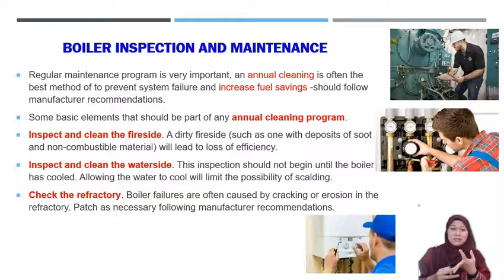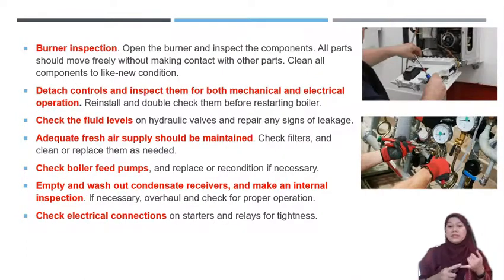So the material used for the vessel must be in good condition. Burner inspection is very important. Is every part of the component clean? Is there any problem? You have to check. And you also check both the mechanical and electrical operation of the boiler itself.